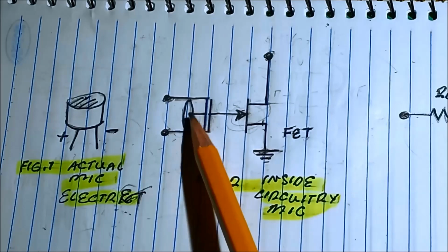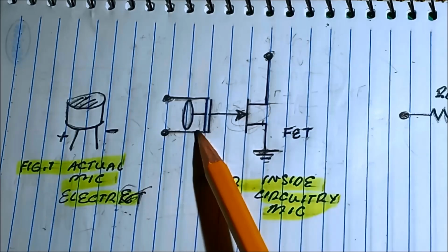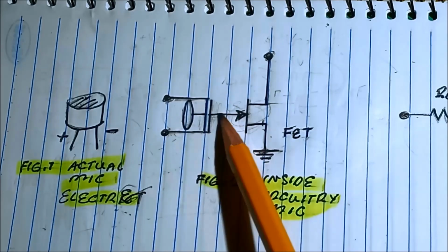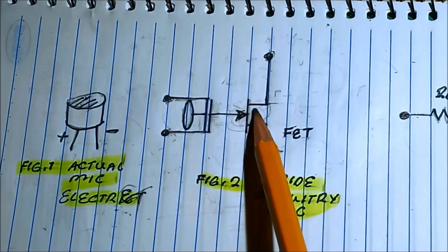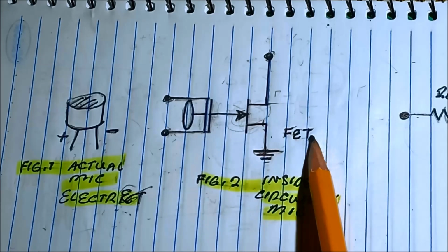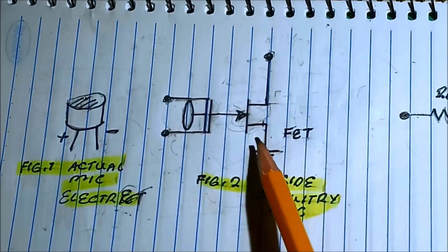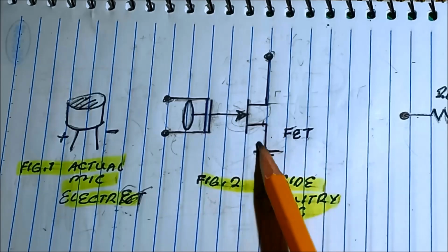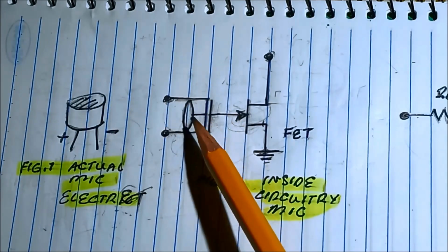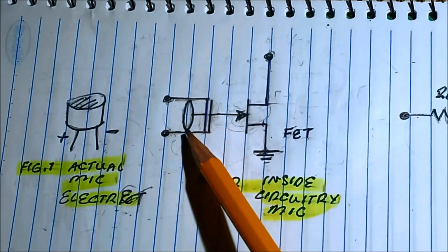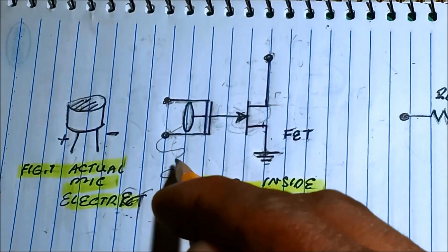The use of this diaphragm is to create a vibration being picked up by the plates, converting it into electric current. So driving this field effect transistor, in this case, this transistor acts as a mini preamp to the vibration produced when there is music.